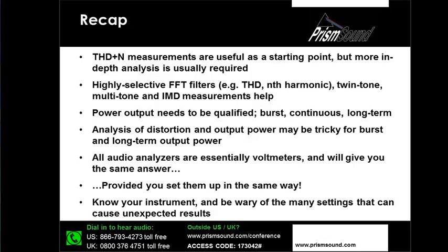Know its characteristics, its input voltage limitations. You should get to know the schematics of the inputs and outputs if they're provided, or at least a high-level architectural diagram if that's provided, so that you can understand what it is that you're measuring and how to connect your test system to your device, which may or may not be trivial.